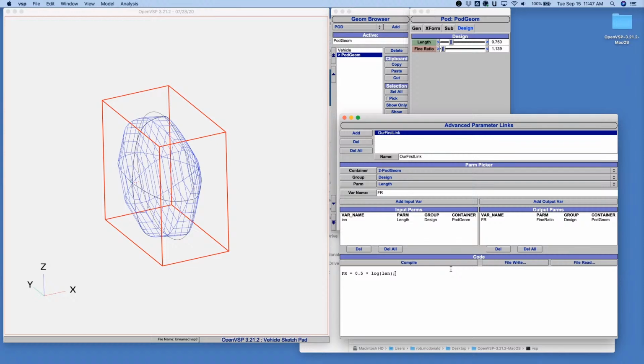The example shown earlier made disk loading a user-defined input parameter, along with the gross weight of the vehicle, and it automatically calculates the diameter of your disks so that you always have models that match the intended disk loading.